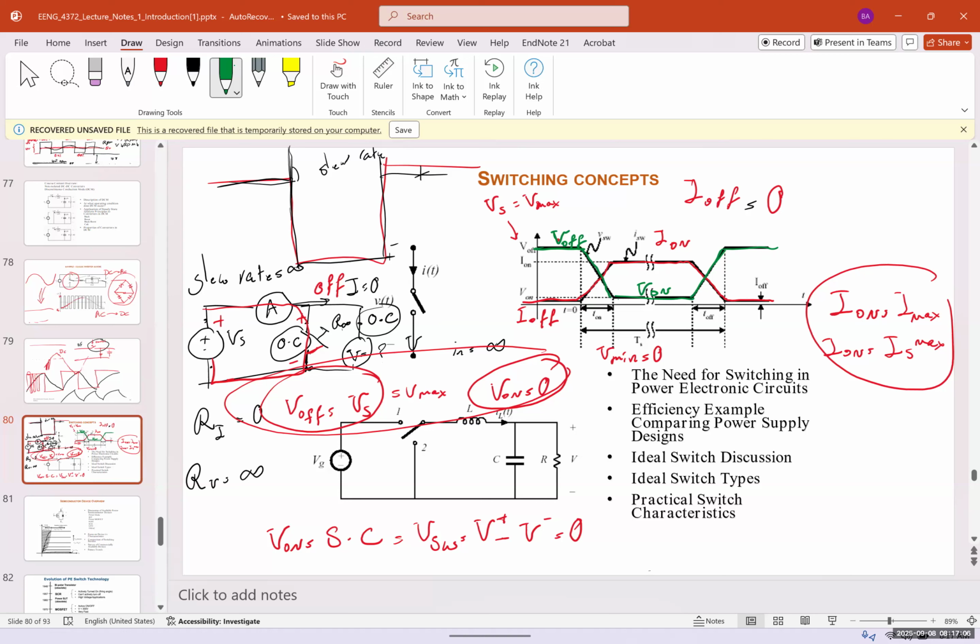So we get this. Now the slew rate is, and the transition time when we turn it on and off, we want this in an ideal situation, this would be square, would be something like this. We would go immediately from maximum voltage to minimal, and minimal current to maximum. And the transition would be immediate. But obviously these switches have physical limitations, and therefore we're going to have a non-ideal situation, which would have, again, the slew rate that I think you remember from LIC.